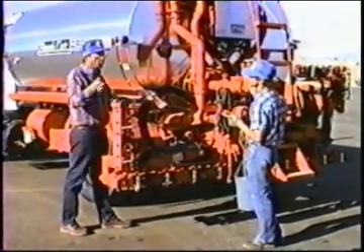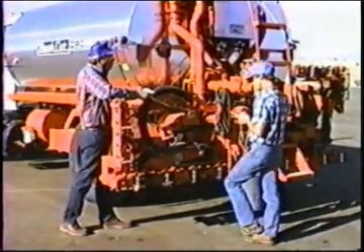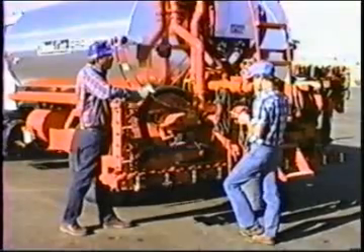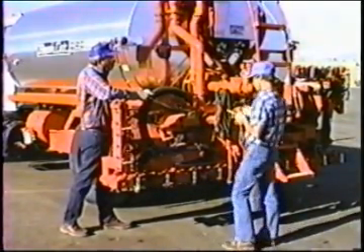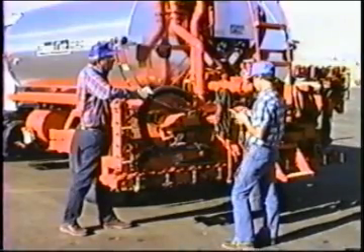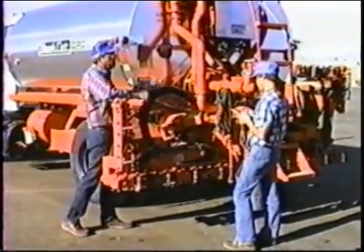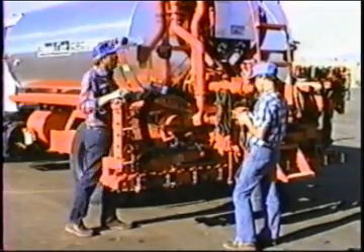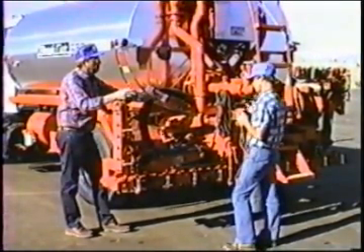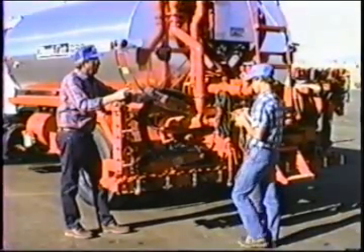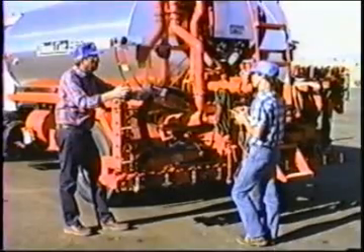Let's say on this one we're going to do this parking lot, and this is a manual machine. We would say, okay, the most we can spread is 16 feet wide. So 0.25, 400 feet per minute, 16 feet wide. I see 180 gallons per minute. Do you agree there? Okay, if we're going to do this manually, we would run the truck at 400 feet per minute, dial in 180 gallons per minute, because now we've got enough for the maximum width.